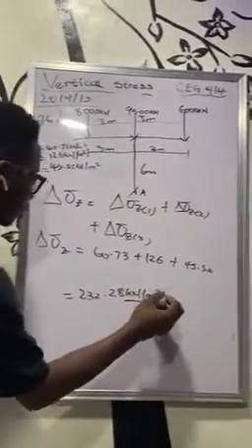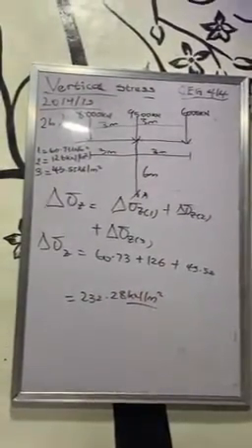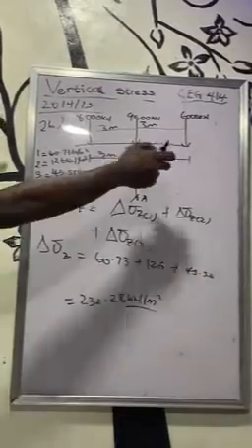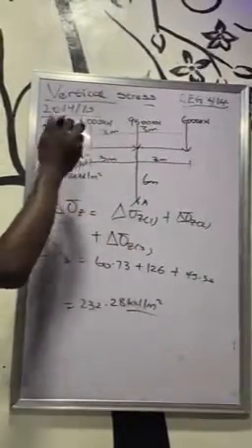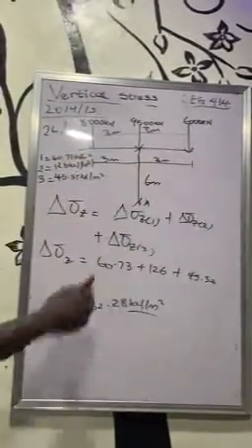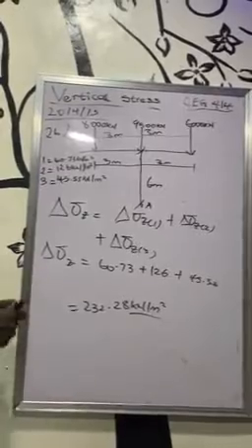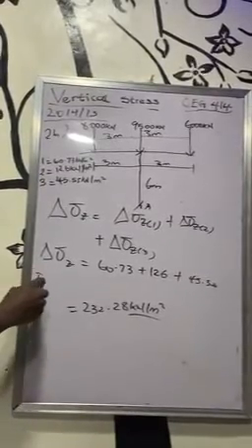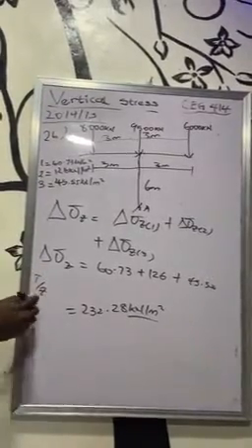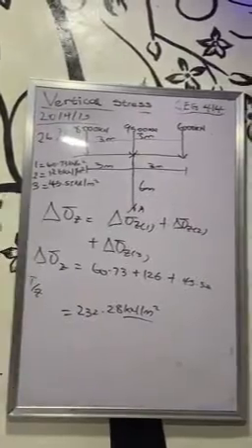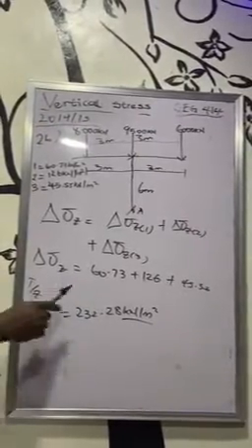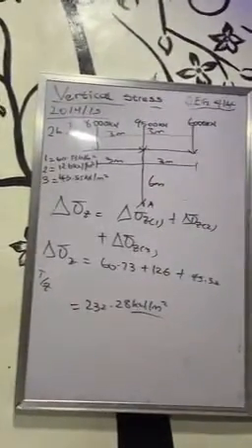And this is very important, don't forget. Point load again, 3 point loads. Add 3 of them together. We found one for this, one for this, one for this. Influence factor I for a point load is dependent on R over Z. We found all our influence factors, multiply them by the P over Z square. We got these 3, added them together. That's the end of this question.